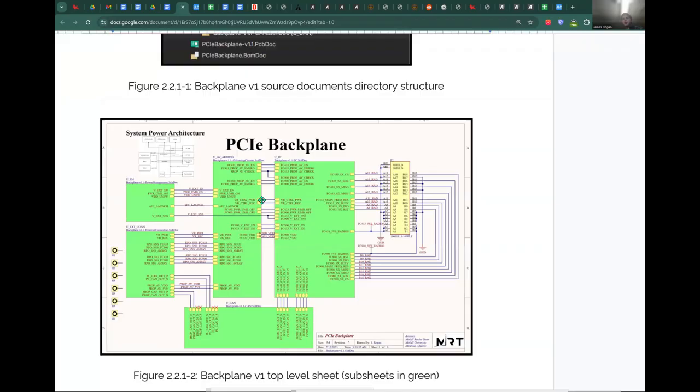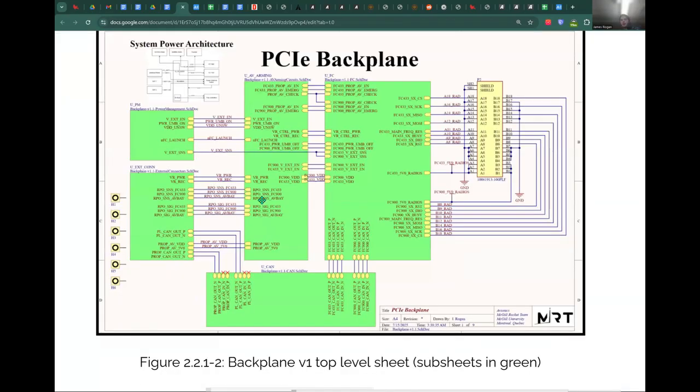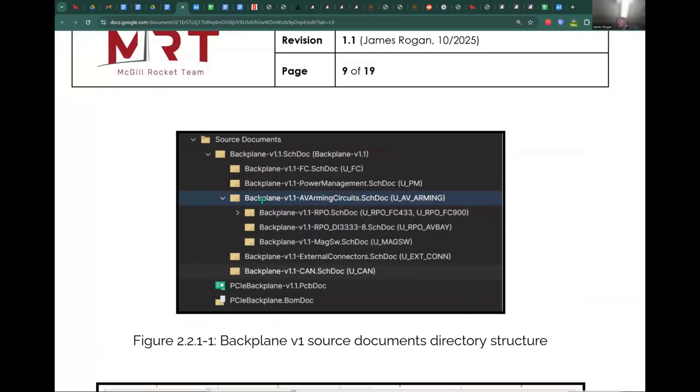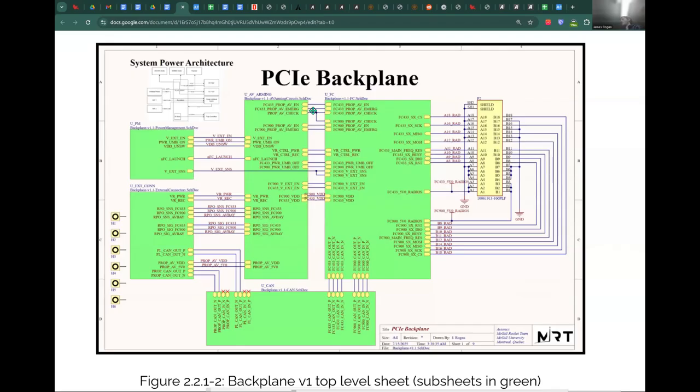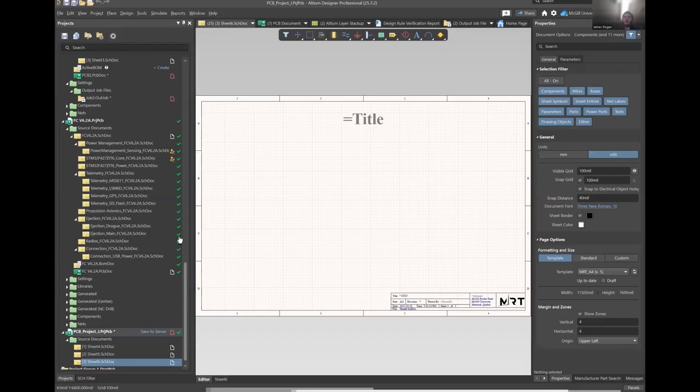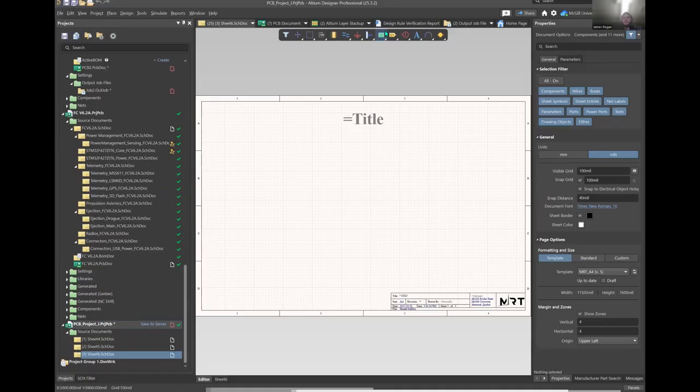As an example, this is sort of what I mean. You have hierarchical schematic sets here where you have the top level schematic, and then you have ones that go down, and then you can define all of your connections in between sheets in this way. So I'm going to show just how to configure that. You have your project with 3 sheets in it. You can just go and add a sheet symbol, and then you can just do that twice.